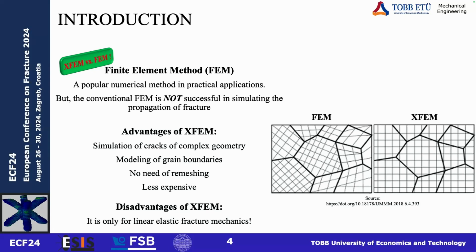No need for remeshing, and it's less expensive than other conventional finite element methods. Disadvantage of the XFEM is it's only for linear elastic fracture mechanics. And in this figure, you can compare the meshing pattern used in conventional finite element method and XFEM.